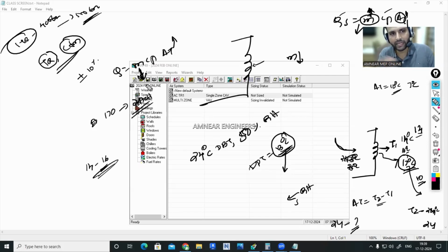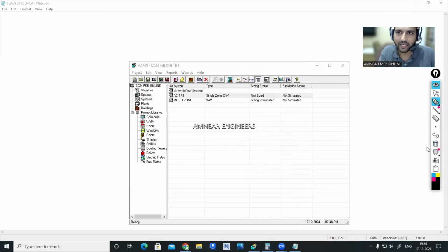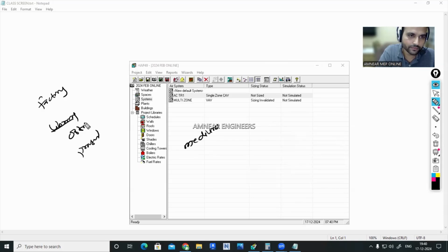So that's why plus or minus 10% difference from the load is fine for machine selection. And also when we are selecting the machine, whether medium speed, low speed or high speed selection has to be done. Always we have to select with the medium speed, but that is also conditional only. For example, I'm designing a factory building, I'm designing an office, I'm designing a prayer room.